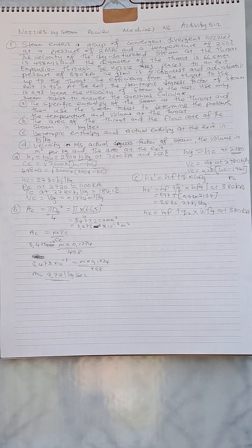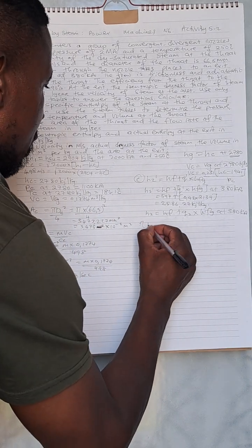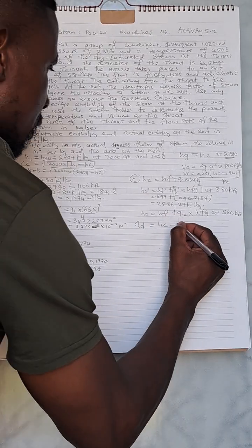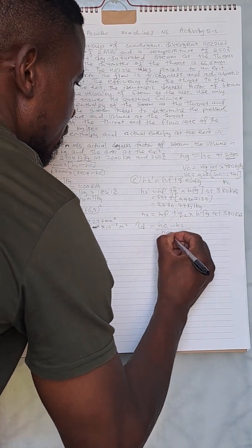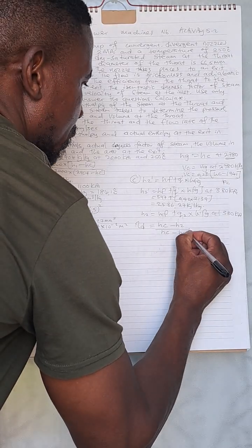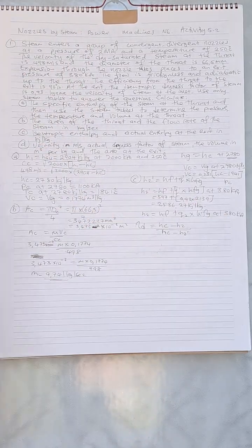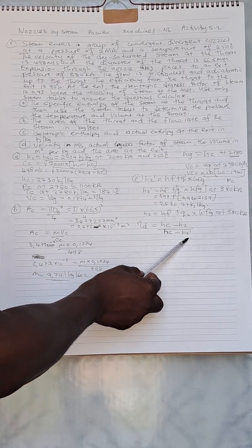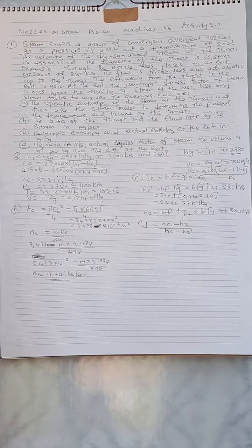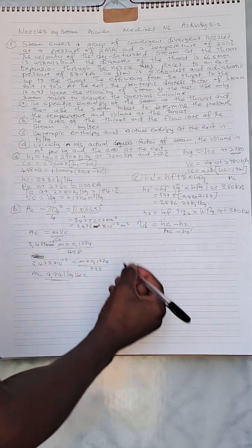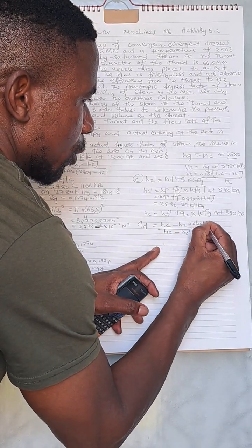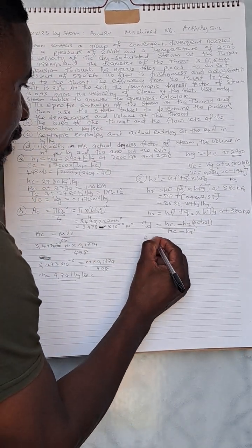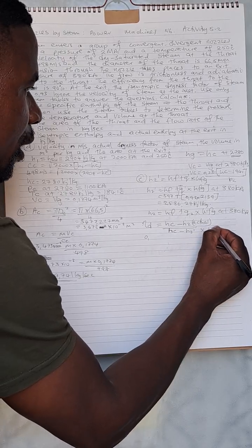So we can use that formula which says efficiency in the divergent part equals HC minus H2 over HC minus our H2 prime. We have our efficiency, we have our H2 prime, we have our HC. So it's easy for us to get our H2 actual. That's what we are looking for. Efficiency was given as 90%. We divide by 100 because remember this is times 100%.